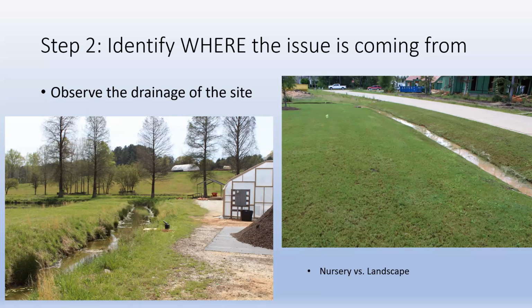And a little pro tip, back in my landscaping days, we'd always go check sites when it was raining. That way we could see where the ponding was occurring, where the flooding was occurring. And especially when we're regrading soil or really trying to make things better that way, it gives us a good idea of where, in fact, that water is going.